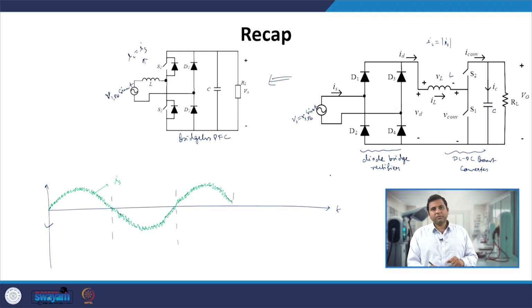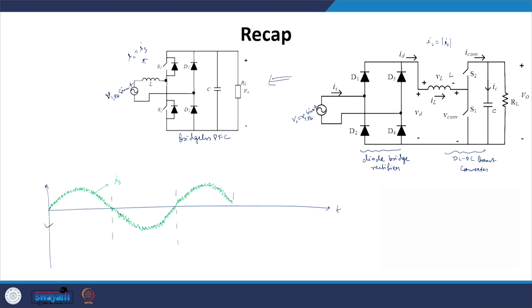In the closed loop control, we have seen two things. One, obviously, is average current control, where we kept the switching frequency of the devices S1 and S2 constant. The inductor current has some average value with a ripple riding over it, and that ensures the switching cycle average variation has sinusoidal behavior, so we get the actual current with sinusoidal variation and high frequency ripple riding over it.